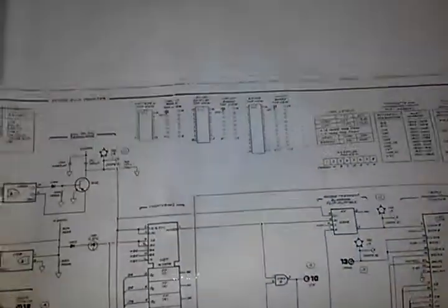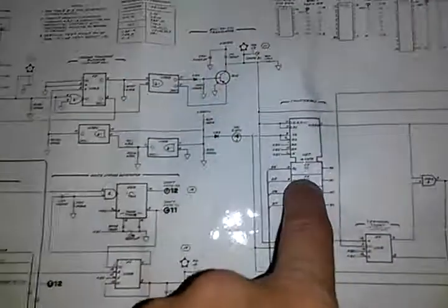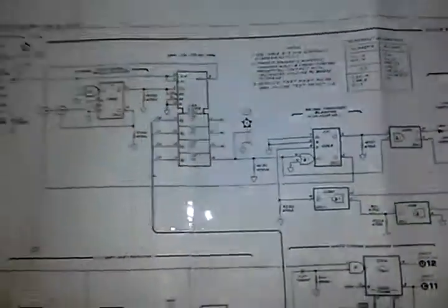and then you get a lock. The point is that every time this circuit counts, it does a total count, a terminal count, and that terminal count is 100 hertz. It should come to here, and there's a pulse that's sent here. Now, what is interesting is that once that terminal count is achieved, everything is reset. And from that point forward, except for the first count that this counter and this counter go through, this functions as a divide by 16, and this functions as a divide by 16. But it only does that after its first cycle.